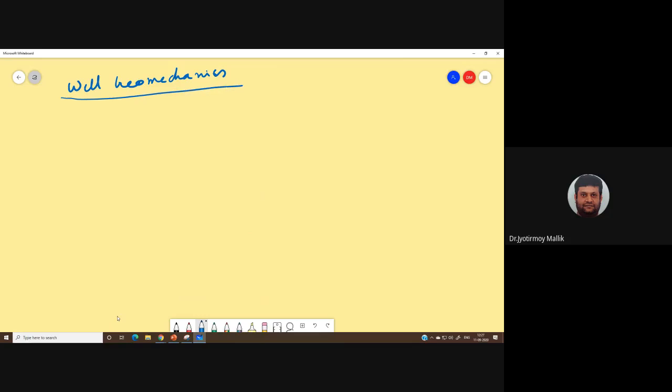We had been introduced to the concept of three stresses: SV, S capital H, and S small h in the last lecture. And we also talked about the pore pressure or the fluid pressure. We wrote it as PP. And we have drawn some preliminary pressure depth diagrams.